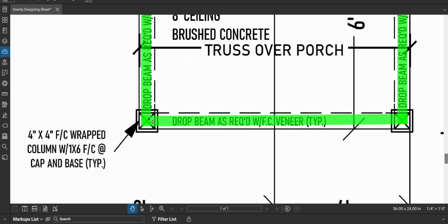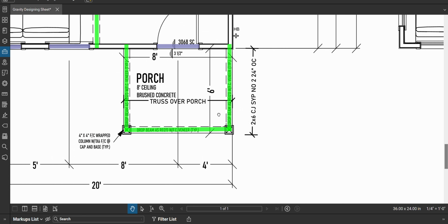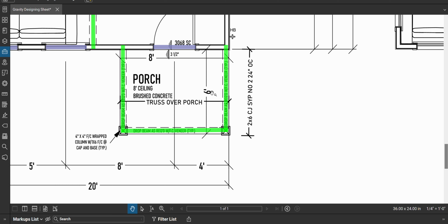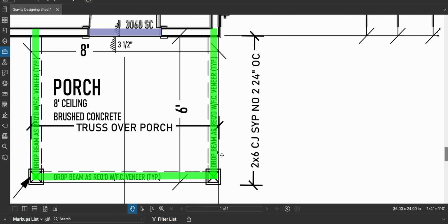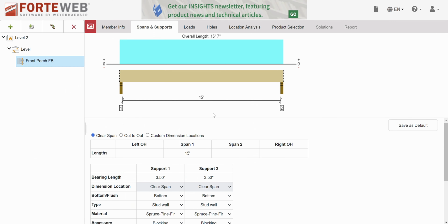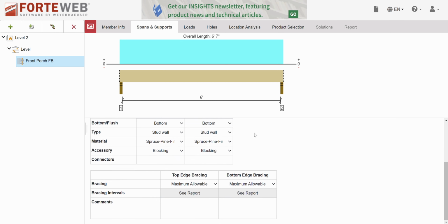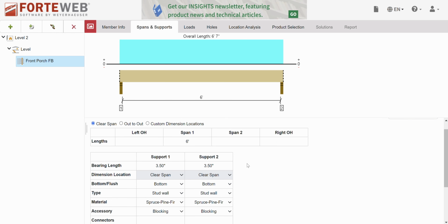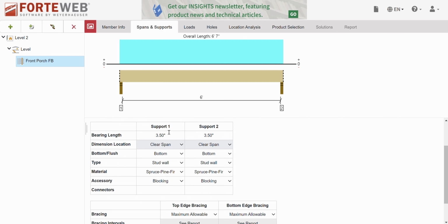Actually, it'll be a 3.5-inch post most likely, so let's not do that. The span of this is not going to matter at this short of a length, so we're just going to call it 6 feet, and I'm going to be conservative. Is it actually spanning 6 feet? No, it's spanning less, but we're going to call it 6 feet because it's always better to be conservative and be stronger. All right, so I got a 6-foot span.